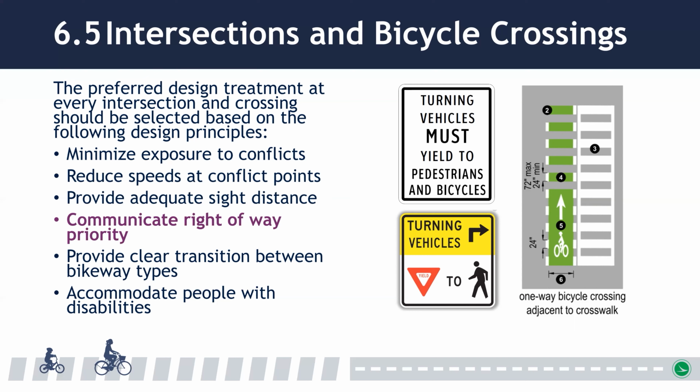These traffic control devices may include marked pedestrian crossings on shared use paths, marked bicycle crossings or lane extensions at driveways and intersections, regulatory or warning signs for motorists and bicyclists at crossings, merge locations, or other locations where conflicts may occur, and signalization. Regulatory and warning signs will depend on the type of bikeway, the lane configuration, and other roadway characteristics. Different intersection layout scenarios are discussed in the subsequent sections of the guide.